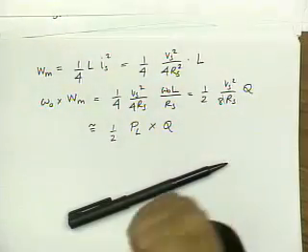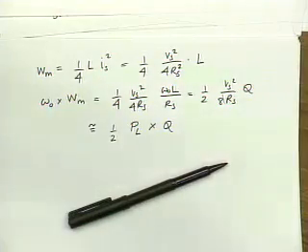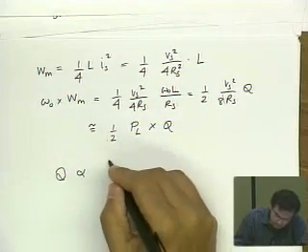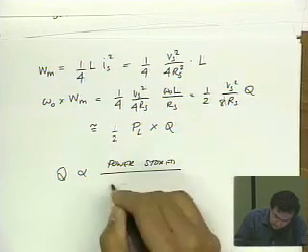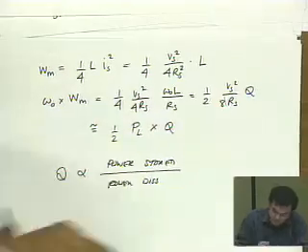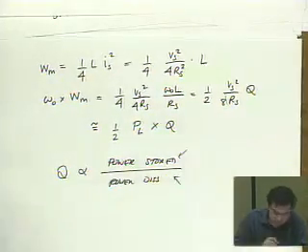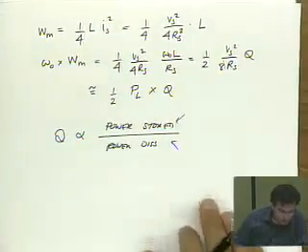So we could come back and redefine the quality factor. In fact, the more general definition of quality factor is that quality factor, Q, is proportional to the power stored divided by the power dissipated. So this is a much more fundamental definition of quality factor. It turns out for second order circuits, these different definitions are actually equivalent. But let me not get distracted too much.